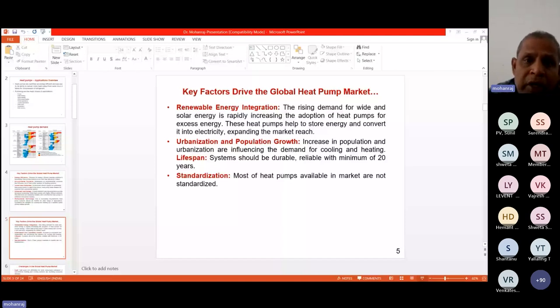When we go for carbon dioxide, it's very essential to have a very strong system to withstand the high operating pressure. And when we go for propane R290 or propylene R1270, we have to take care of the flammability issues. So these are the major drawbacks we are going to face in future when identifying working fluids. Now China has introduced a new refrigerant, R1233ZE, which is going to work up to 150 degrees centigrade. At 140 plus degrees centigrade, it is possible to use.